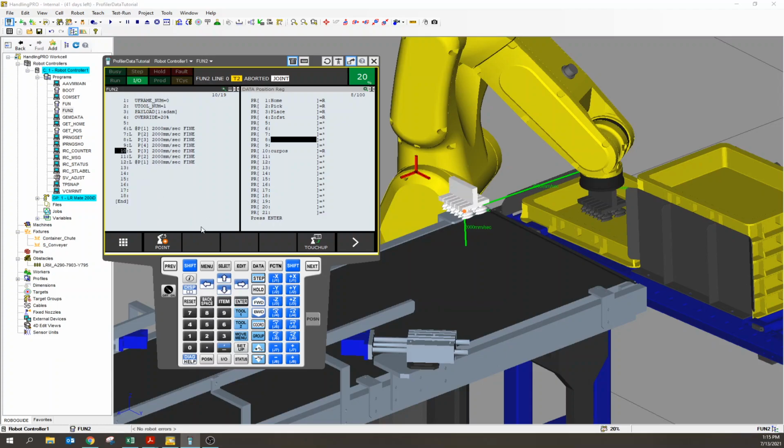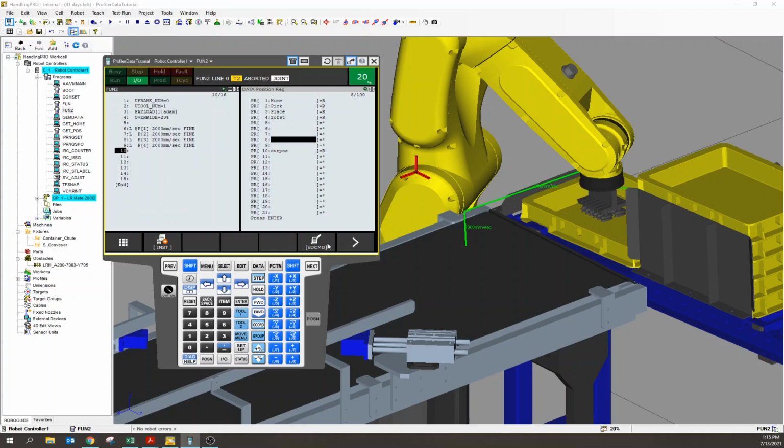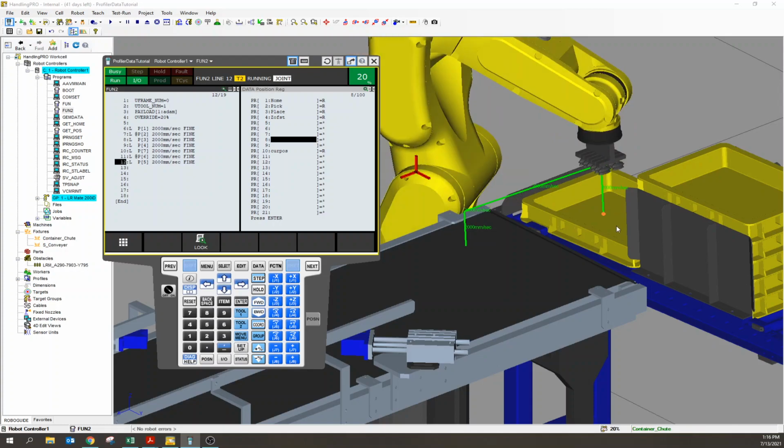And again, I'll show you one last thing before we wrap this up. Let me delete these lines. If I wanted to run this program without reusing 1, 2, 3, just so I'm thoroughly teaching you guys, paste, next, I can say reverse position, but instead of remembering the IDs, instead of reversing the position IDs, I will just reverse positions. So now look what I get. I get 1, 2, 3, 4, 7, 6, 5. It looks the same on robot path. 1, 2, 3, 4, 7, 6, 5. You can still see it follows the up, down, over, down path.